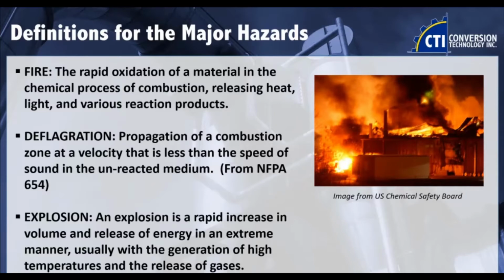Each dust or particulate has what's known as the MEC, or minimum explosive concentration. That's the concentration that's needed in a given volume for there to be the potential for a deflagration to occur. You need the availability of oxygen as well as an ignition source. Basically, the fire triangle turns into the explosion pentagon, which I'll go over in a couple slides. So with all four of those occurrences present, you do have the potential for a deflagration hazard.